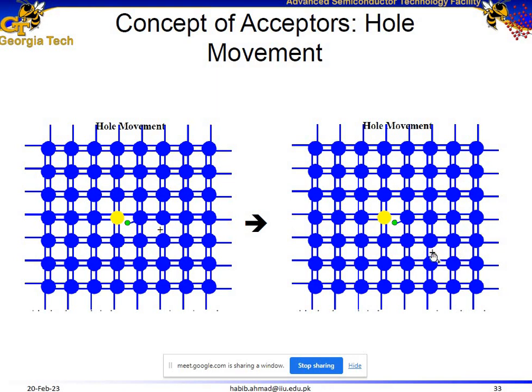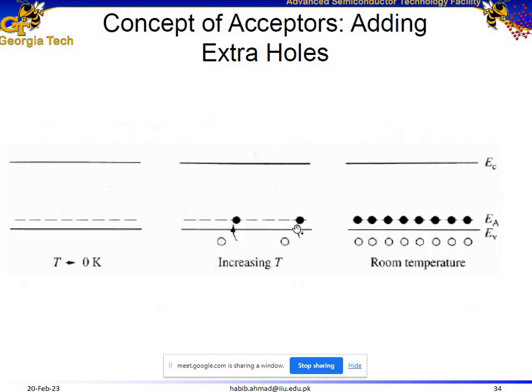And similarly, another electron would jump from here into this previous part, but then the hole keeps moving to another adjacent silicon atom. So effectively the hole is moving towards the right and the electron is moving towards the left. And what do we need in semiconductors for conduction? We need carriers to move around inside the crystal. If carriers are moving around inside the crystal lattice, it means that it's going to result in conduction or current for us. And that is important. That is what we need.